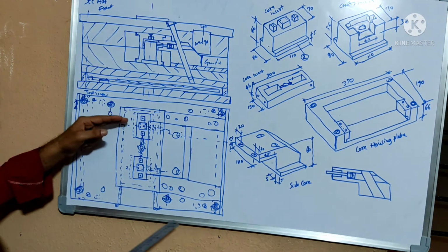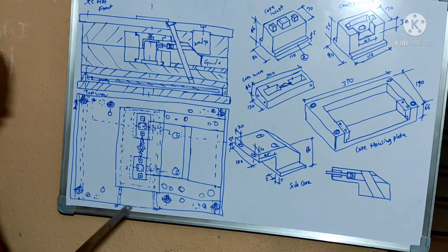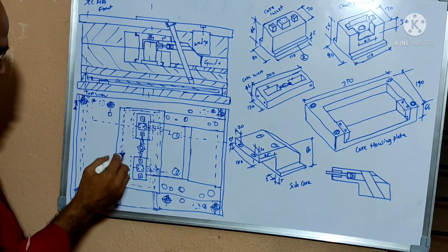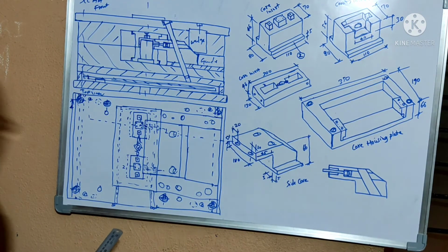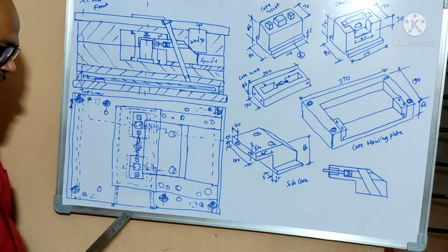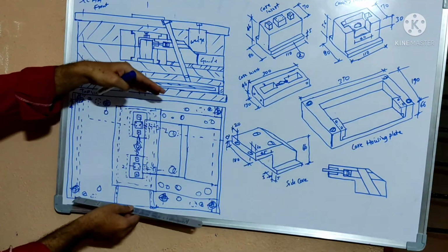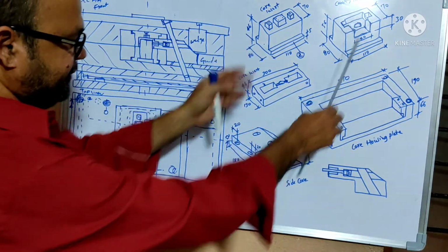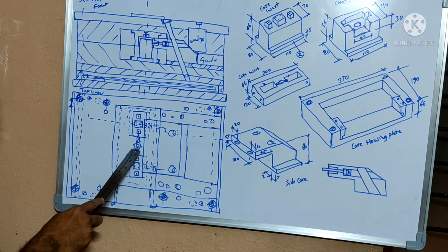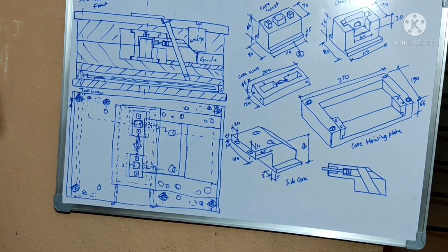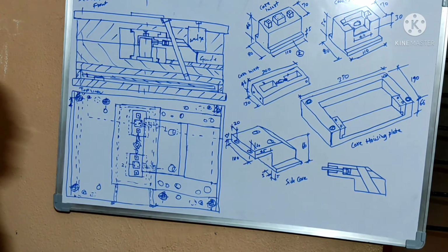If possible, while drawing in the drawing sheet, you can go for the side view of the tool, where the sprue puller bush and ejector pins with the core cavity can be shown.